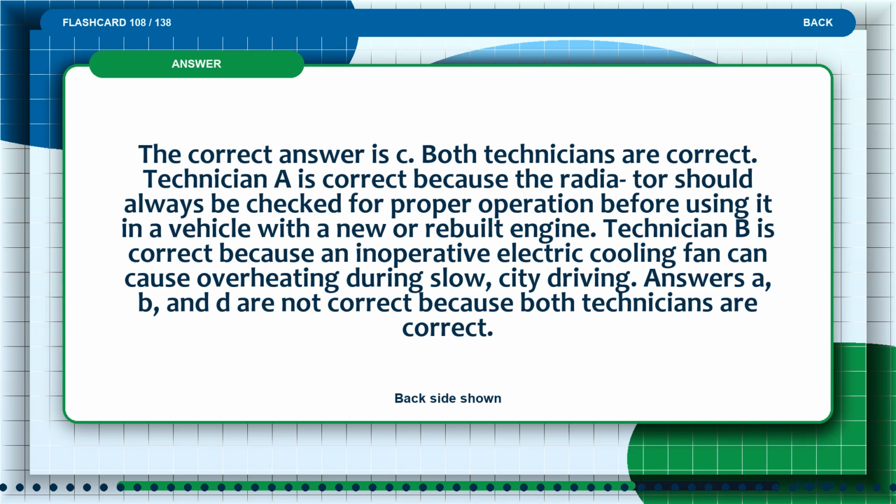The correct answer is C. Both technicians are correct. Technician A is correct because the radiator should always be checked for proper operation before using it in a vehicle with a new or rebuilt engine. Technician B is correct because an inoperative electric cooling fan can cause overheating during slow city driving. Answers A, B, and D are not correct because both technicians are correct.